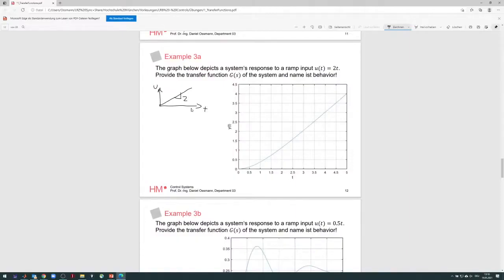Okay, what do we get out in steady state? We get out a value of, this must be 1. This is 1, right? So our gain of that transfer function must be 0.5, because we need to go from 2 to 1. If I'm not mistaken, it looks like 1, yes. It's going to be 0.5.